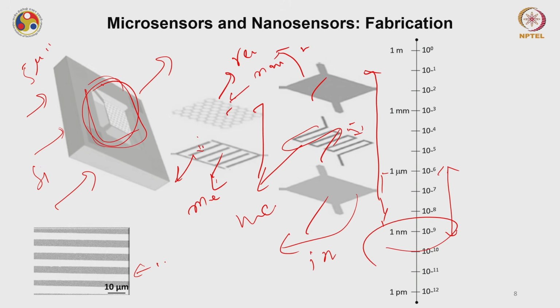So over the next few minutes, let's talk about some of the fabrication techniques that are utilized in fabricating such devices. This is a typical device that we fabricate regularly. This is a metal line. The brighter lines that you are seeing are the platinum lines, and the black part is SiO2. So this has been patterned successfully on a wafer. We'll see what a wafer is and how this patterning can be achieved.